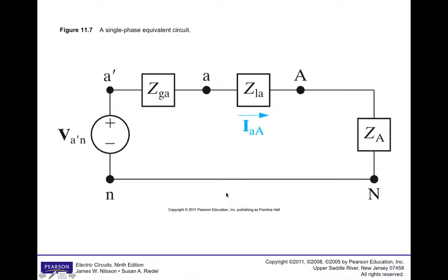So this is one of the practical issues that can plague three-phase systems: if your load or your generator or your line has a fault, and it doesn't have to be a major fault, it can be a minor flaw that makes some little difference between the impedances in A, B, and C where you're slightly off balance, then you get current in the neutral wire, and that can feed back into your generator and create problems, and it also wastes energy.